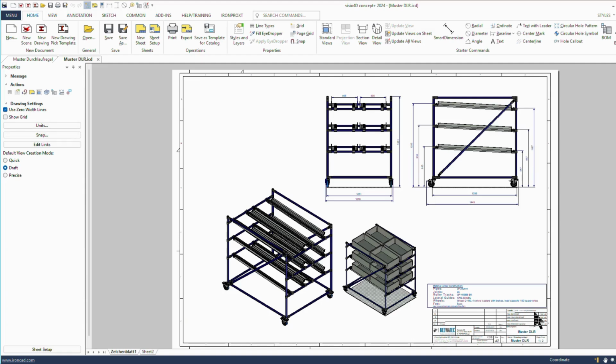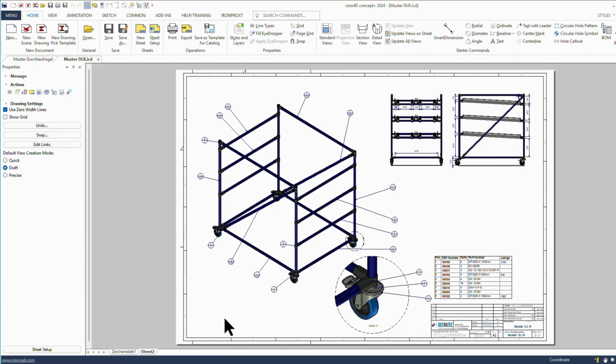We then opened a second page by creating a construction drawing. The construction drawing differs from the standard overview or functional drawing sheet. Dimensions from joints to joints are marked on it, so that the fitter can assemble the structure on site using these measurements. We've created an isometric view here, complete with a corresponding parts list, so that you can see relatively quickly which pipes are fitted where.